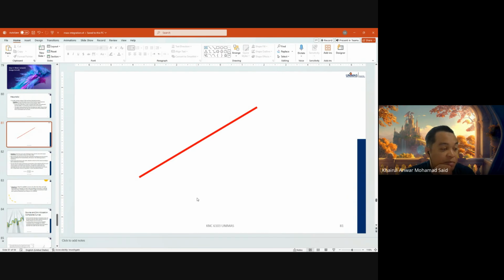So step four begins with the boundary line. We take the pinch concentration we calculated in step three. Example, the 700 ppm pinch in problem 8. Draw the line. So below the pinch is the clean zone where the concentrations are low and purity demand is high.